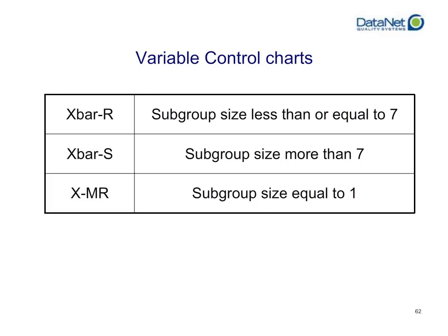We'll talk about that more as we go through other examples, as well as in the capability analysis part of the course. But for now, we're going to continue on. Xbar and S is very similar to Xbar and R. The top chart you're plotting is the average of your subgroup.